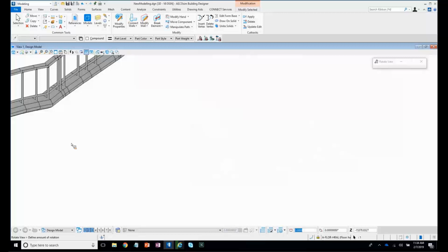Let's go over here to surfaces. So actually we'll start with curves. As I said, a lot of stuff is history based now. If I place a curve, let's say I place a curve such as that on the screen, and we copy it, let's say four times, and then we go to our surfaces, we can loft a surface along this. Okay, so there's our surface. It looks like this. So we've just developed some history within this object.